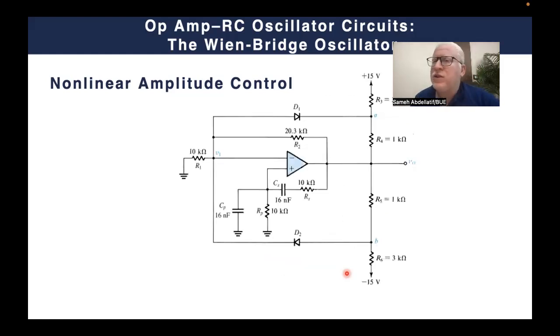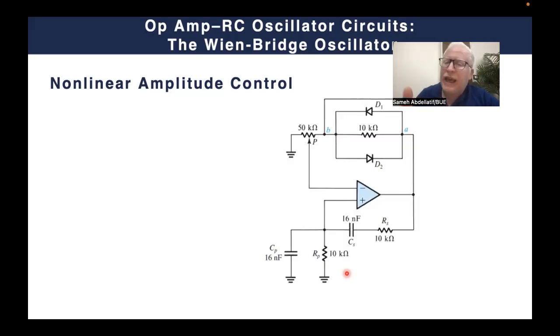So this was one of the first architectures to do an oscillator, but again, we can use this to do an oscillator. So generally speaking, when you find something like that in your exam paper, just start to think in a very organized manner. First of all, we know that an oscillator is typically a combination of an amplifier with a positive feedback frequency selection network. So your first step always is to distinguish between your amplifier network and your frequency selection network. So simply speaking, I am going to use my annotation now.